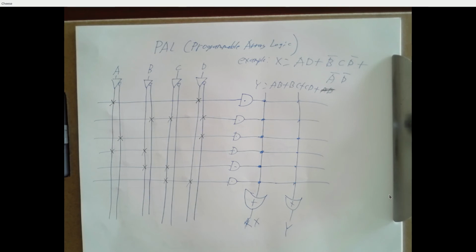Okay, so why does it melt? Well, current, voltage, multiply them, you get power. Power comes off as heat. You heat up metal enough, it'll melt. So a fuse is a piece of metal made out of a material that melts at a very low temperature, a couple of 100 degrees maybe. And you tune it so that if you send, say, 15 amps of current at 120 volts through this piece of metal, it'll get so hot that the metal will melt. And when it melts, it stops conducting electricity because there's a gap in the metal.